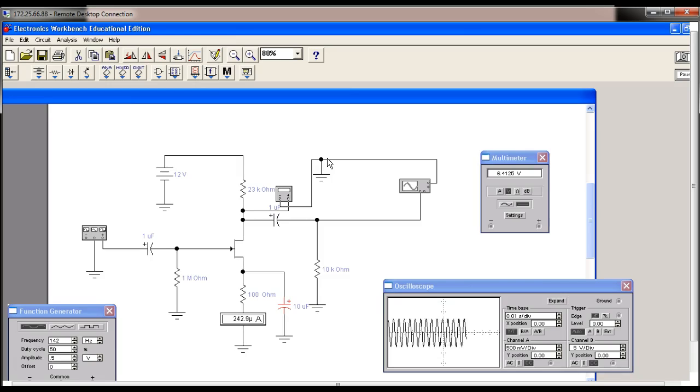It's extremely hard to get on a bipolar transistor because there are so many variables when the current comes into the base and splits up and moves around. With an FET, we don't have to bias it with a voltage divider. What we've got right here is a 1 megohm resistance, which would hopefully match the impedance of this generator right here.